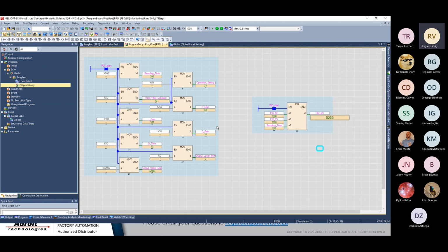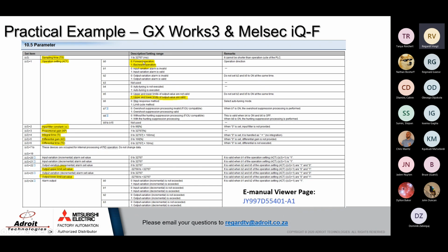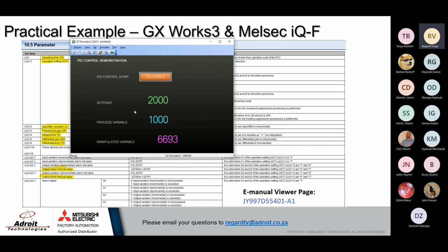Okay. So if we had this in forward control, it would have reacted if your set point was higher, your set point was lower in the first variable. But it wasn't reacting because you're already the lowest you can be. Your VSD is already running at its maximum to try to keep the pressure, for instance, or your valve is already open to its maximum to try and fill the tank. So that is why it didn't react.